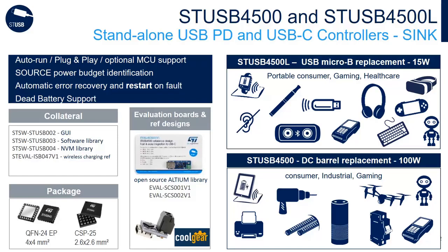Although it's not necessary, thanks again to the auto-run capability, the ST USB 4500 does support an I2C interface and can be controlled or configured by a local microcontroller during runtime. So ST does provide optional software for those applications where more control is warranted or the designer wants to change the configuration on the fly.